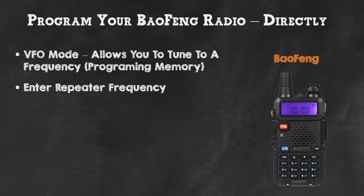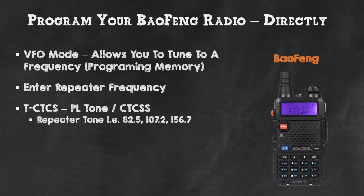So you want to enter the repeater frequency, which we got from Repeater Book. This is how they look at it. We want to put in the tone. So they're going to call it T-CTCS. This is the PL tone, the CTCSS tone, or basically the tone. This is the description Baofeng uses to enter that in. So this is where we put like the 82.5, the 107.2 that came from the repeater book that I just showed you.